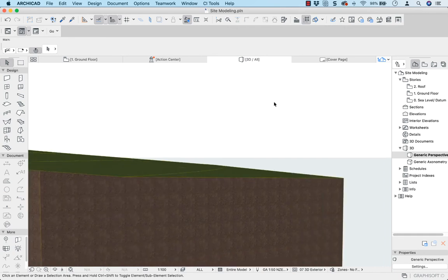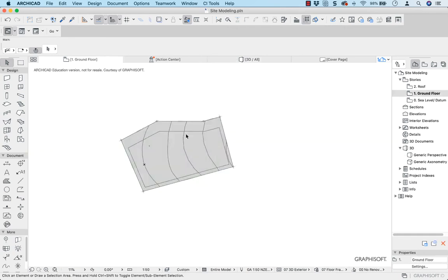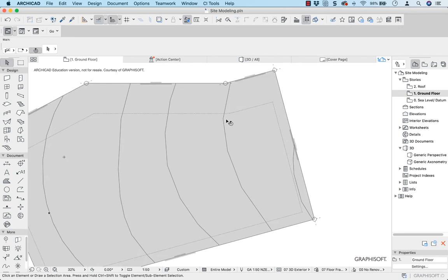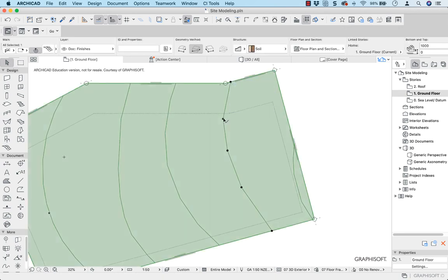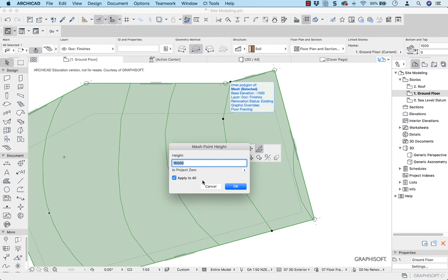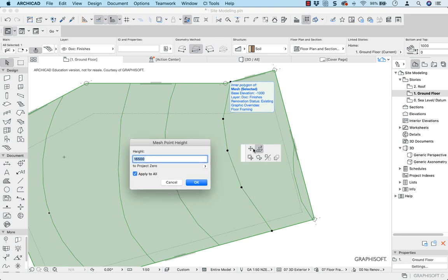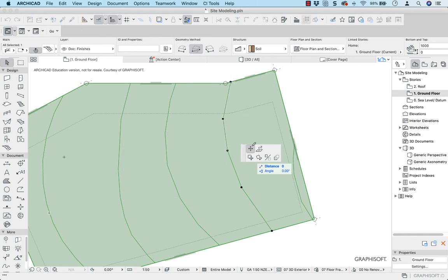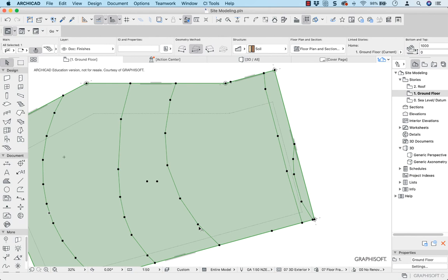Now if you want to move those contours, you certainly can. So if we need to redo our site or do some site modeling, for example, I can click on one of these node points and I can change to a different option like that one, and then I can move my contours around. So I could start here and move that contour down there, move this one to here, and I could make a retaining wall style.